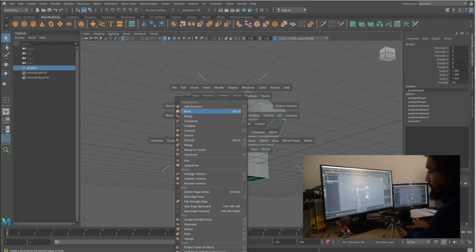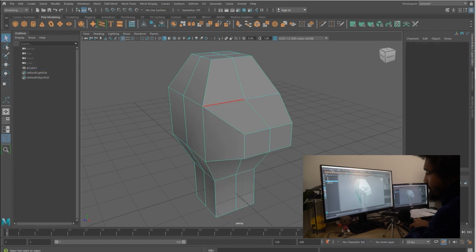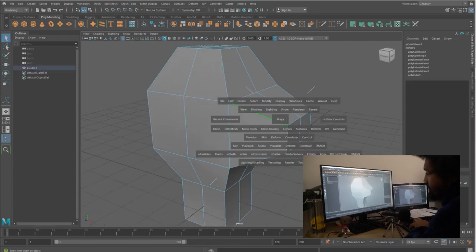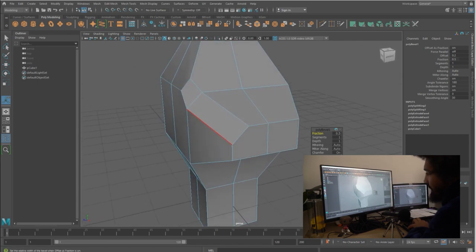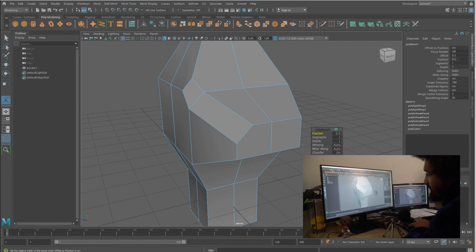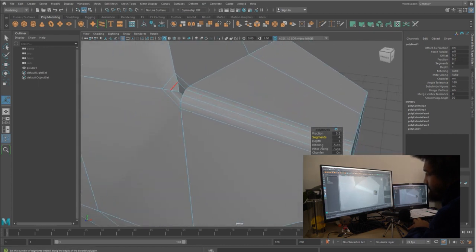We can do as well what we call the bevel. So bevel, basically, look at this edge here. If you just take this edge, for example, and you do an edit mesh bevel, you see it's creating another face based on the edge. So you can do multiple fractions, so it's like the size, but you can see multiple segments. So it's creating all the options, and as you see, when you go to 4 segments, a triangle pops here. So that means it can't generate a face of 4. So this is a face of 4. You have here enough to do stuff.